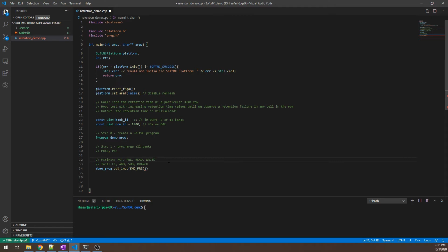So we want to operate the DRAM at very high frequency, and here the trick is that we operate FPGA logic slower, let's say at F frequency, and then we operate the DRAM bus at 4F frequency. How this works is at each FPGA cycle, the FPGA can, but doesn't have to necessarily, issue 4 DDR4 commands in a single cycle.